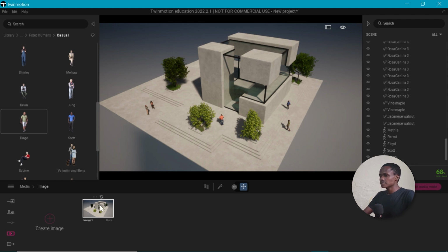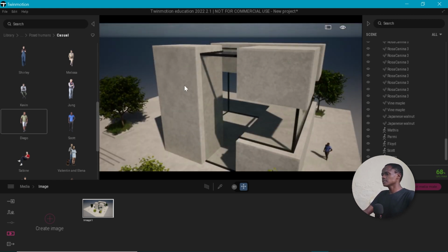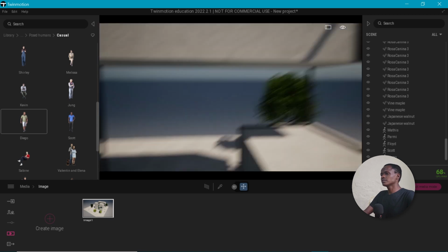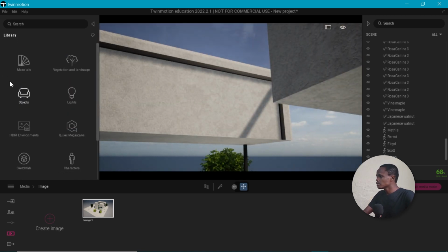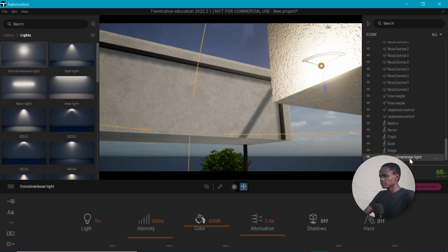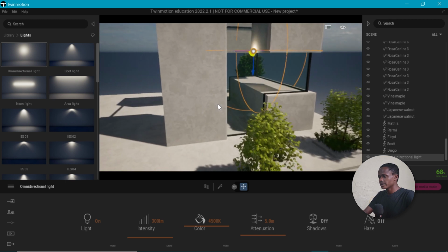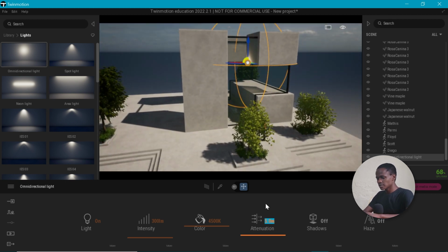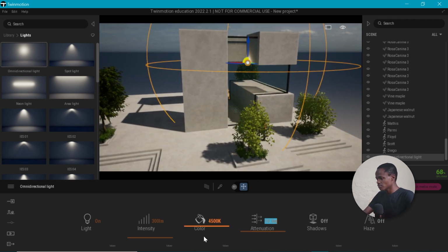And now let's add some lights inside here that will put in some nice character. So let's go under here, lights, and then put a light in here. And don't forget, it's the last thing that you will be at the bottom. And let's attenuate it by I don't know, 10 meters. Great, such that it lights the whole thing. So this, it may need to be like 1,000 lumen. Yeah, that's much bigger.